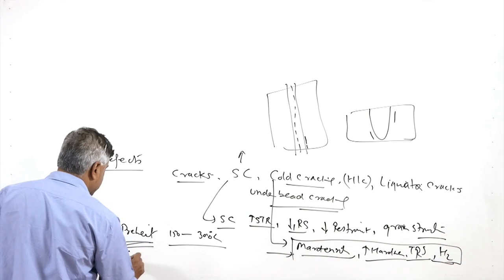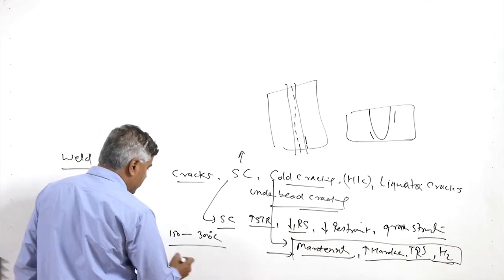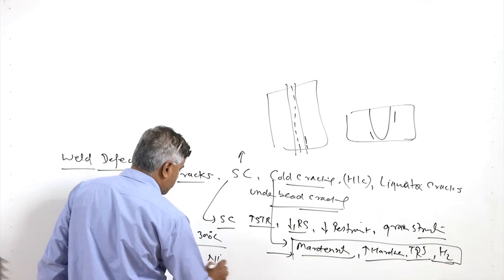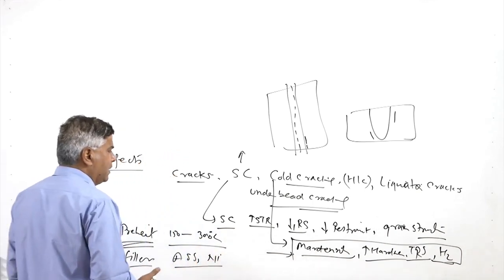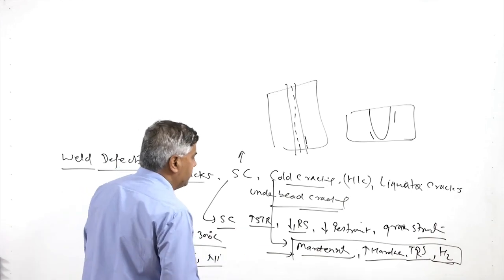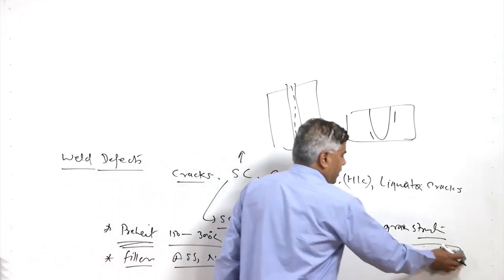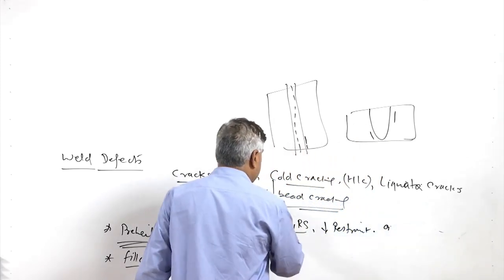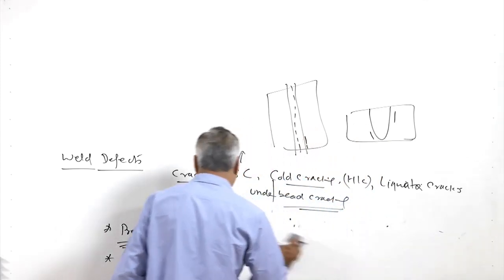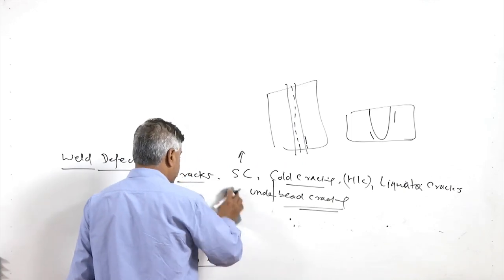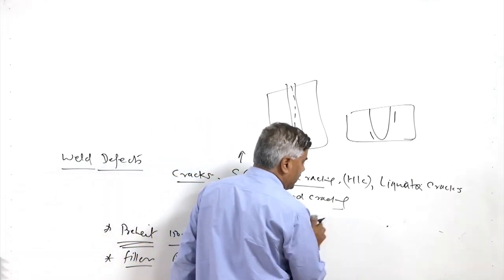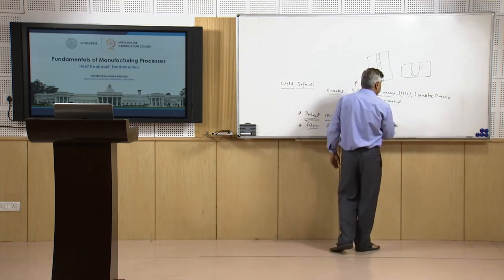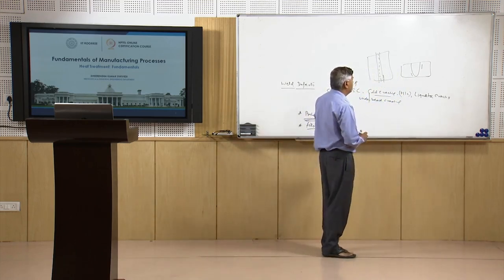Then another is the selection of the suitable filler. Fillers like austenitic stainless steel and the nickel alloys, which can accommodate the hydrogen in the weldment and accommodate the residual stresses easily, are also used for controlling the cold cracking. Because these will help to reduce the residual stresses, as well as accommodate the residual stresses, as well as accommodate the hydrogen which is present in the weld metal.